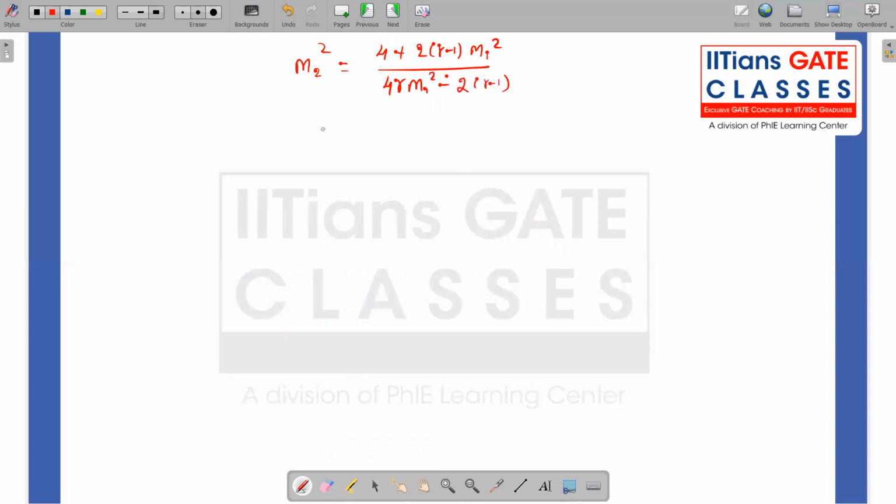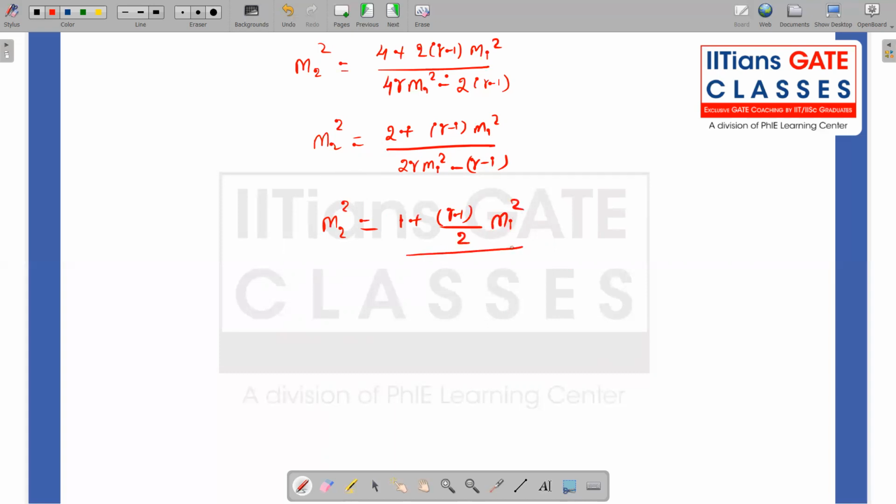So I can take 2 common in this equation. So that gives me m2 square is equal to [2 plus (gamma minus 1) m1 square] divided by [2 times gamma m1 square minus (gamma minus 1)]. Sometimes what people do is write it in terms of a well-known relation, that is 1 plus (gamma minus 1) by 2 times m square form. So to do that, I can take 2 common now. So that gives me m2 square is equal to [1 plus (gamma minus 1) divided by 2 times m1 square] divided by [gamma m1 square minus (gamma minus 1) divided by 2].